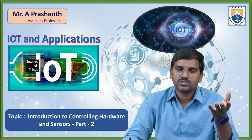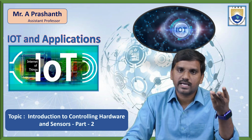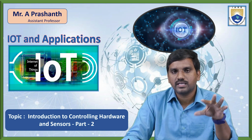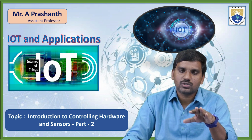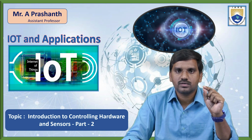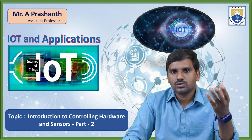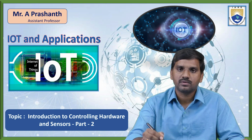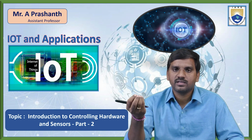Before that, we have some components like the LED, connecting wires, and a microcontroller. After making the connections on the breadboard, we write the code to dump to the microcontroller, with a 1 second delay for blinking the LED. After executing that code, the output comes on the LED: it turns on and off every 1 second.